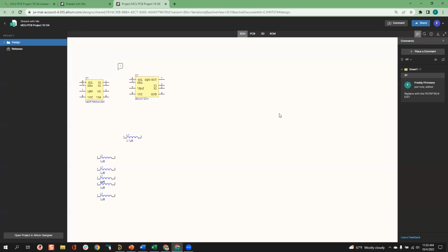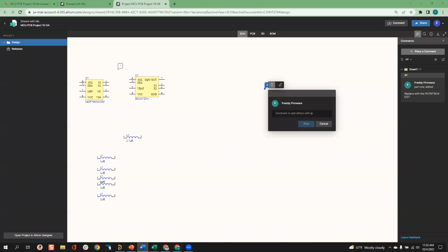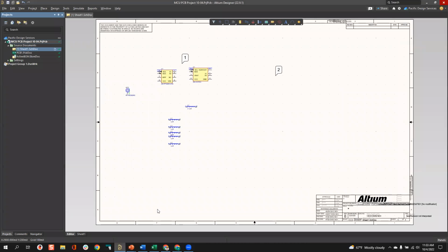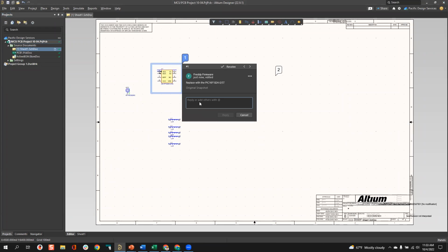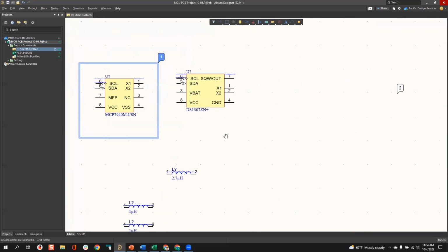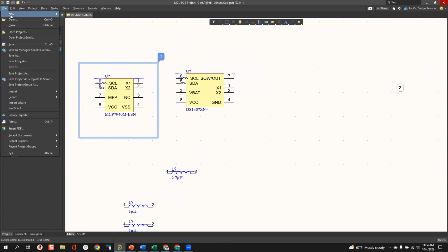All right, so he can also place comments just about anywhere you want, really. So if you say, let's put out a note to everybody, let's make sure we use the same Molex connector, for example, that we did on the previous design, right? So he can start dropping comments in here. So what happens here is that I see those pop up in my Altium right here. And I say, oh, okay, so Fred's online and he wants to go ahead and replace this part with an 1824. Okay. So what I can do is actually go into my manufacturing part search,